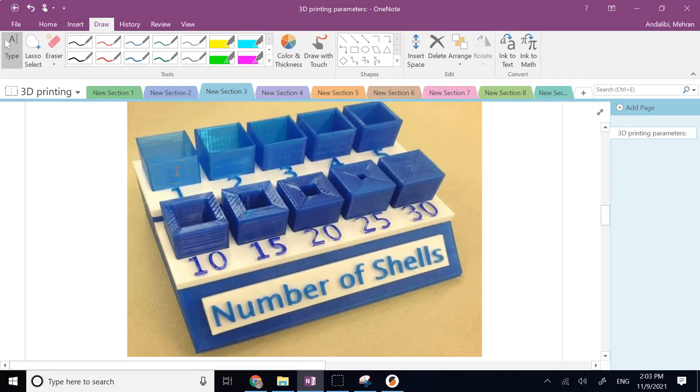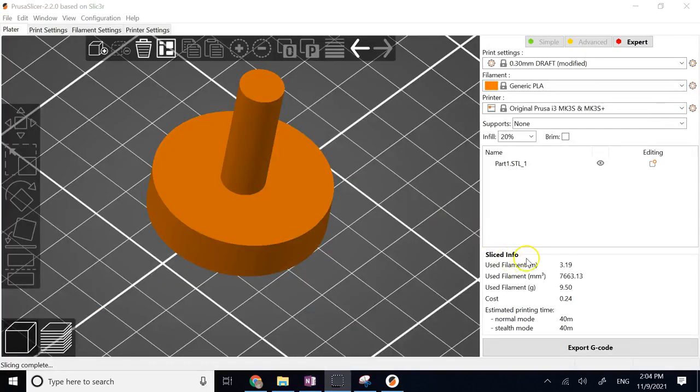Unless you really want it for that reason to be a very, very thin wall, which is sometimes even a little bit transparent, because you can see the light through it to a good extent. There is no reason for something to be one layer, because even with the smallest contact, that one layer 0.4 mil wall thickness will break. So here, let me show you.